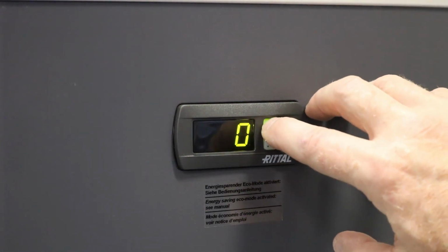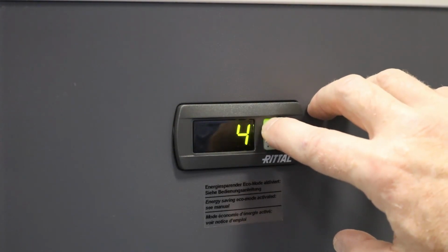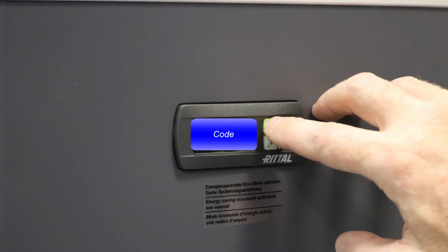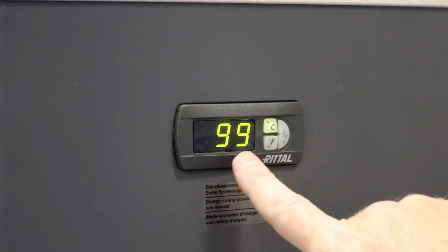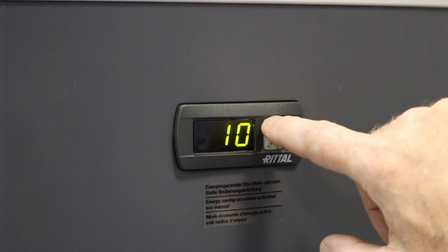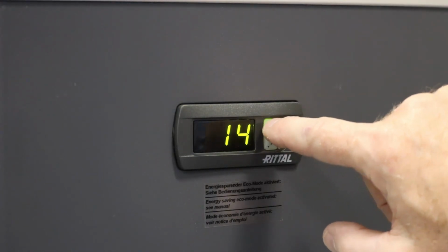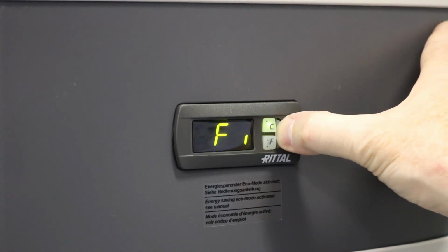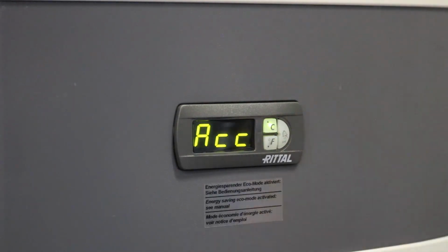It's going to ask me to enter the code. I'm going to block out the code for obvious reasons, but you can go into the instruction manual you have to see what that code is, or you can go online if you've misplaced it and find what that number is. So hitting the button again, it starts with 10. 10 is the lowest threshold level for alarm. So I take 10, I add the 5 from previously to give me 15. And then when I hold the set key down long enough, it's going to give me ACC for accept. Okay, so that's accepted my change.